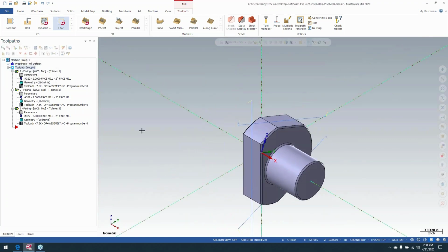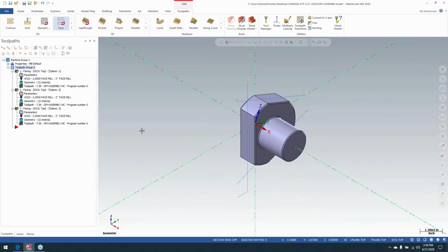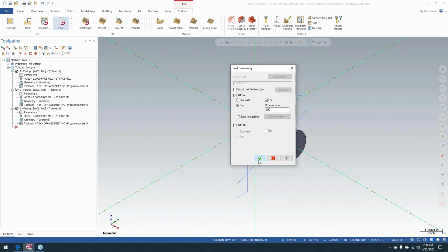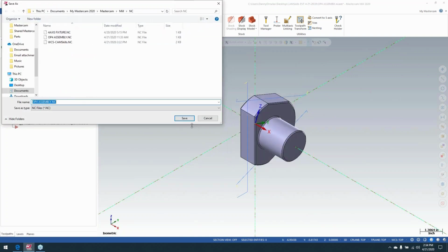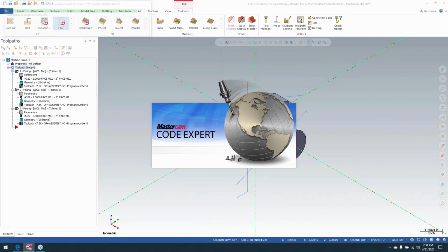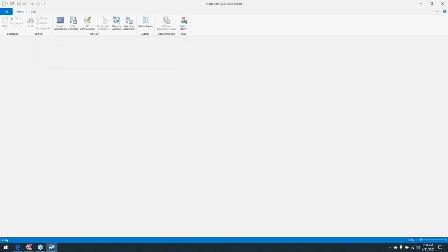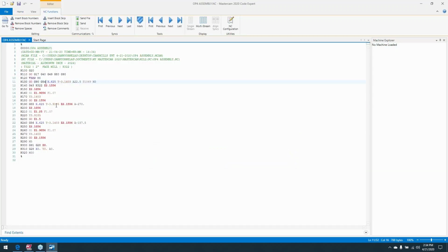Now, a common issue we have with Mastercam, and what feedback we get from customers, is they're doing something like this. You post it out, and just because they're all coming from the same location, they're all at 0, 0, 0, if you're not careful, you'll still get different work coordinates here. So G54 at that angle, you get G55. Now, when you're doing a rotary part like this, you kind of want everything coming from 1 G54. So these we have to get rid of.